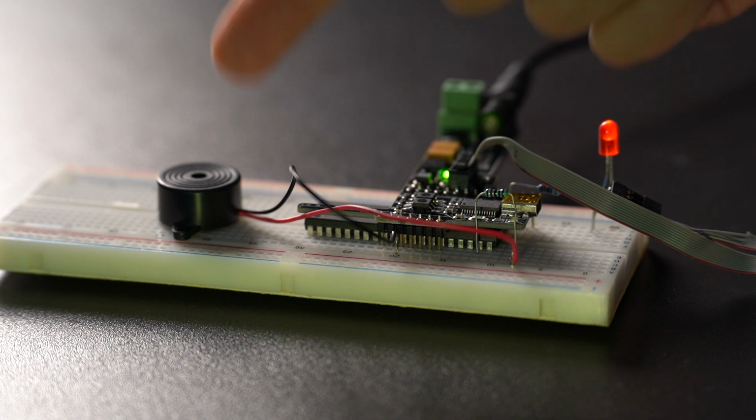Another example software is also available on the website of the curriculum, which can play melodies, of course not through the LED. Let's take a closer look at how it works. Building the hardware isn't too complicated here either. A speaker has to be connected to the microcontroller through a 120 ohm resistor. But now we will use pin 19 on the chip, which is PD5 or OC1A.